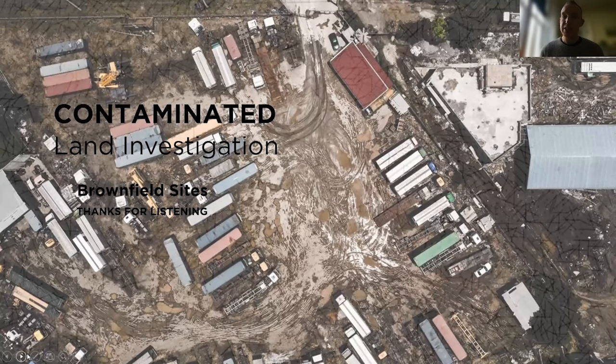We test for these gases by drilling boreholes in the ground and installing a well in them. These wells are a plastic pipe with slots in it that lets gas and groundwater pass through. The pipes are sealed at each end with a tap on the top, and we have specialist monitoring devices that we can plug into that tap, and that will give us an instant reading of what percentage of oxygen, carbon dioxide, methane, and some other gases are in that gas.